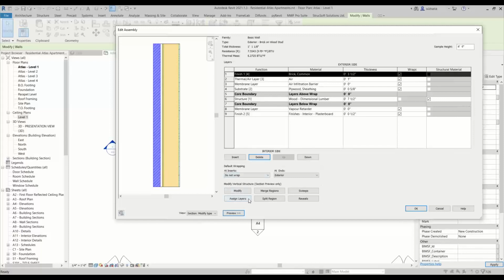And then sometimes also we've seen issues happen for users when they use assign layers, and they assign maybe the bottom half over here to be concrete, and then they have the top half be brick, right? Sometimes when you do that, it causes MWF to break. So we typically recommend, if you do have walls like that, separate your finishes from your actual structural layers, and you should be okay. You could still have your finishes the way you need them to be, and your structural layer will be exactly the way you need it to be for framing with MWF. All right.